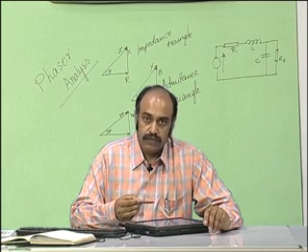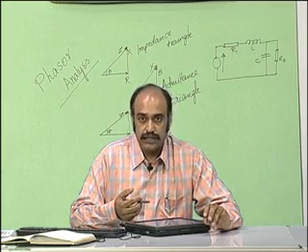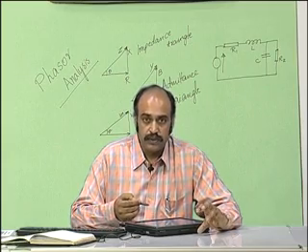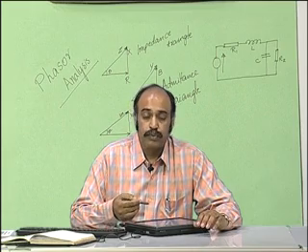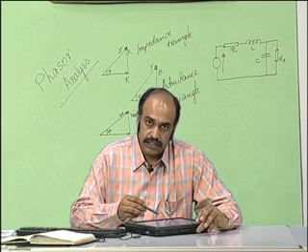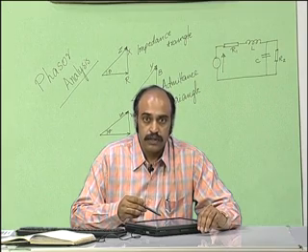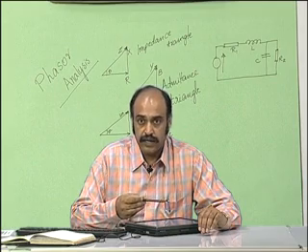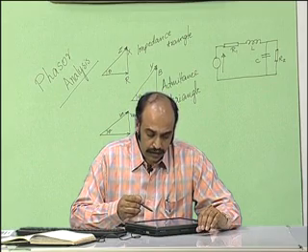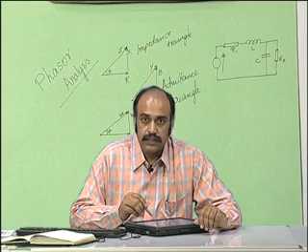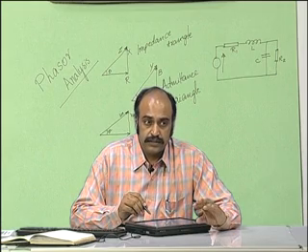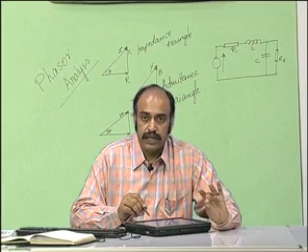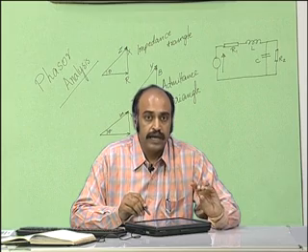But of course, later on when we start covering transformers and induction motors and so on, we will see how these phasor diagrams will grow for more complex topologies of the circuit, but this is the basic that you should know about the phasor diagrams, especially for the R, RC, RL and RLC circuits. At this point, we will conclude the phasor analysis by summarizing that there are three triangles that you need to remember. One is the impedance triangle, the admittance triangle and the power triangle.